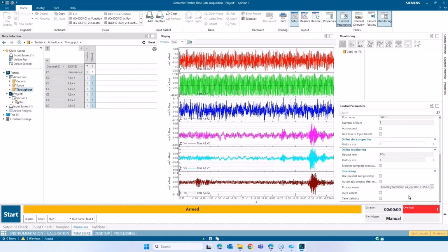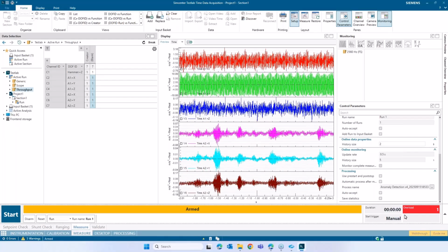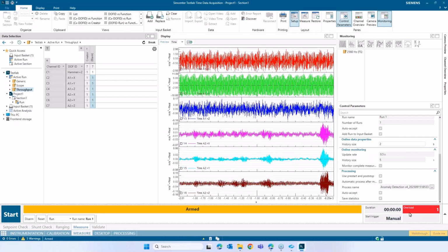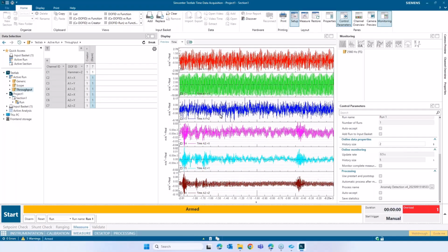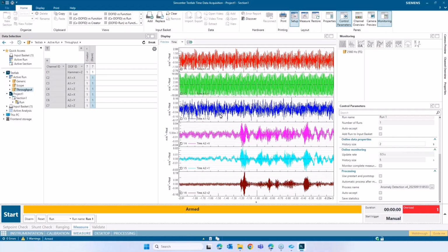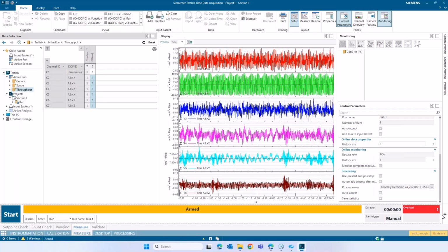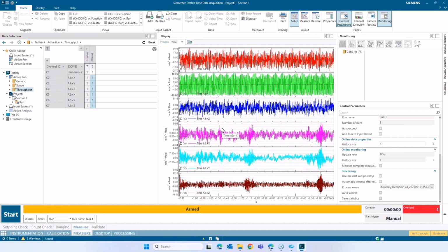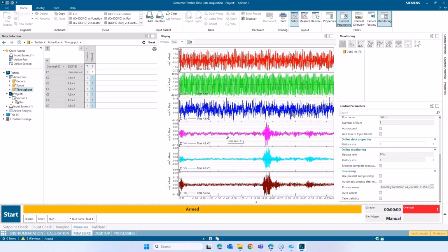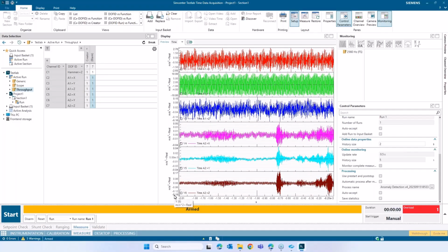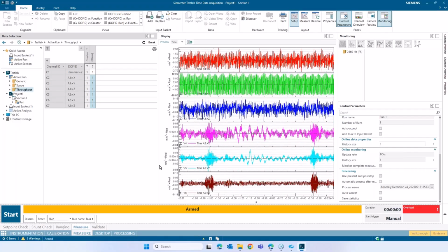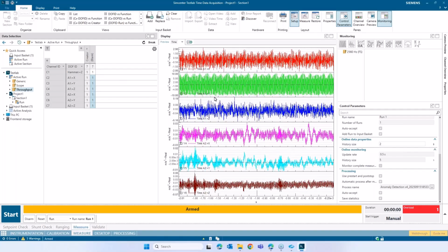We can already see on the bottom right hand corner that one channel is being detected as overload. That is the Z channel of the first accelerometer that I had purposefully disconnected, so it is correctly indicating that. The bottom three channels are the second triaxial accelerometer, which is showing low vibration levels because it is not mounted on the fan. So we can see that live.